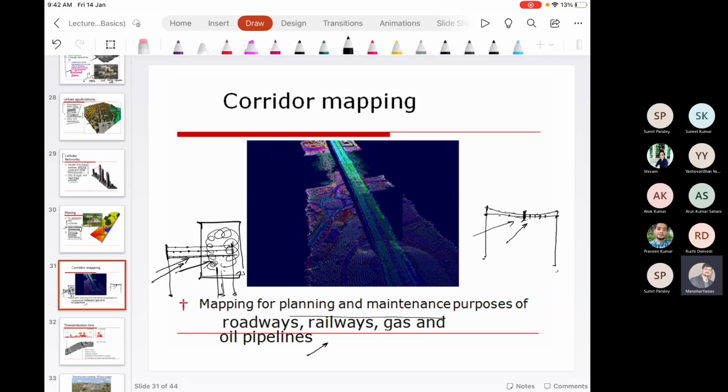Okay. So similarly, we can perform various geometrical analyses. In a power line corridor, we talk about two cases. The first one, the encroachment of tree branches onto the power line, can be identified. And similarly, the various catenaries which pass from one pole to the next pole, their three-dimensional gap can also be identified. And the required maintenance has to be performed on that basis.